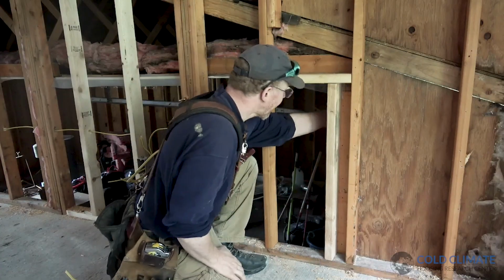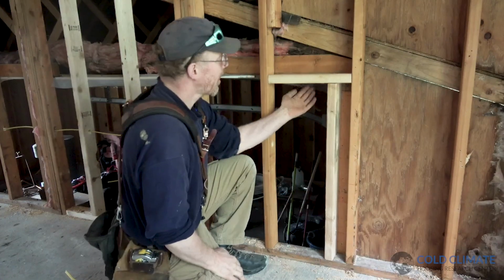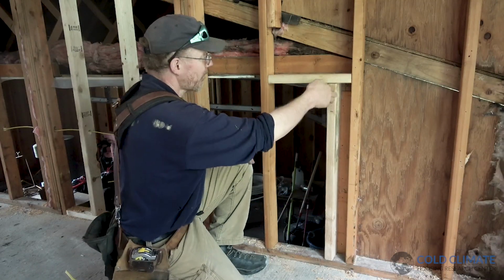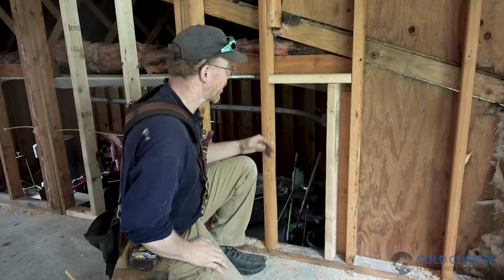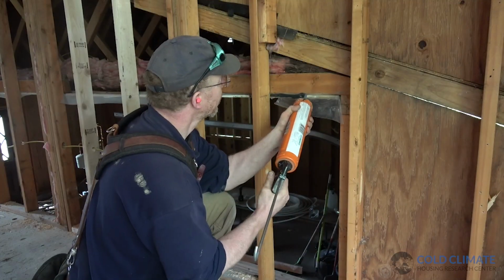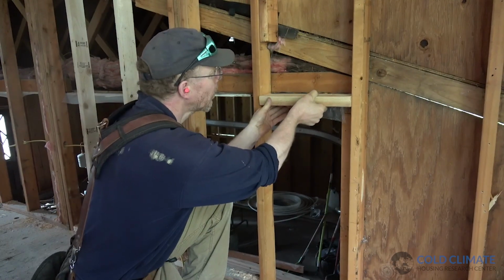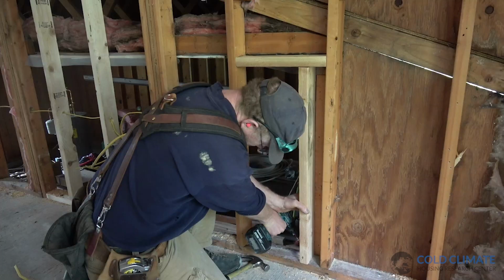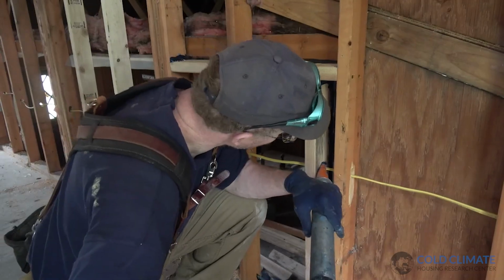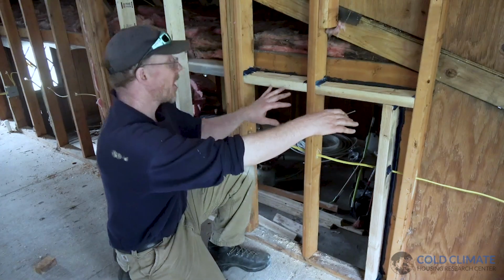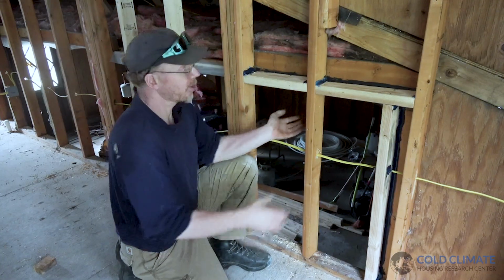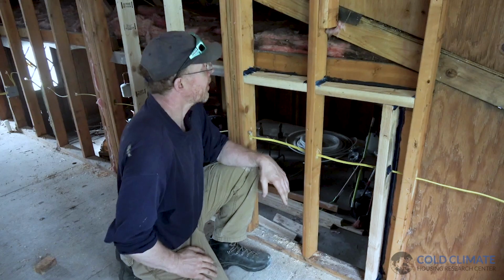And then on this side, the garage vapor retarder can seal to our blocking. And on this side, the house vapor retarder can also seal and transition our thermal and pressure boundaries all the way across here. So we should have a really robust transition from one to the other. I've now installed 2 blocks in the row of blocking that needs to be installed here to transition our garage ceiling pressure boundary to the pressure boundary of our intersecting house wall.